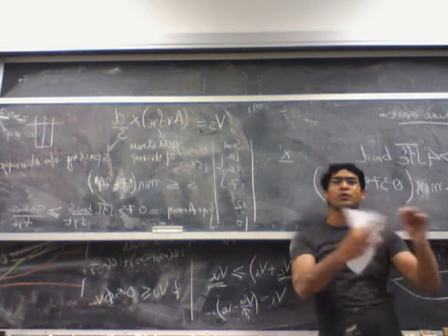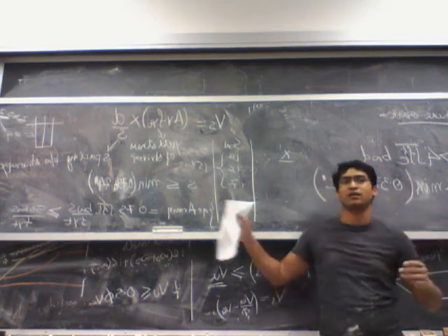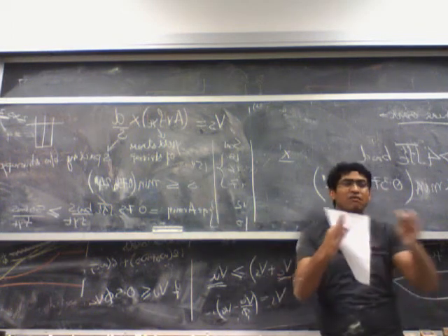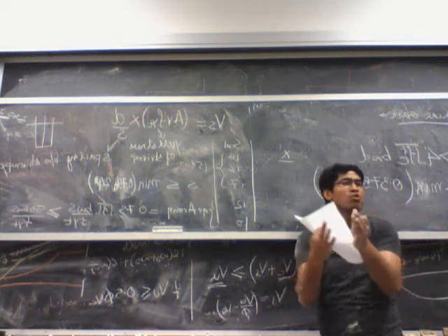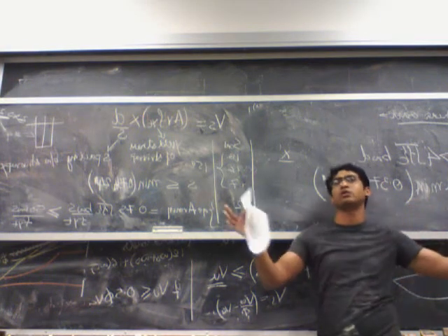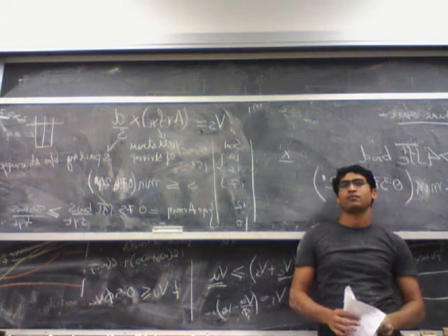And don't make like 10 or 20 sections. Like in a real case, if you're doing a shear design, don't pick several sets of spacing. Make it maybe 2 or maybe 3 sets of spacing. That's it. So one near the midspan and one near the supports.